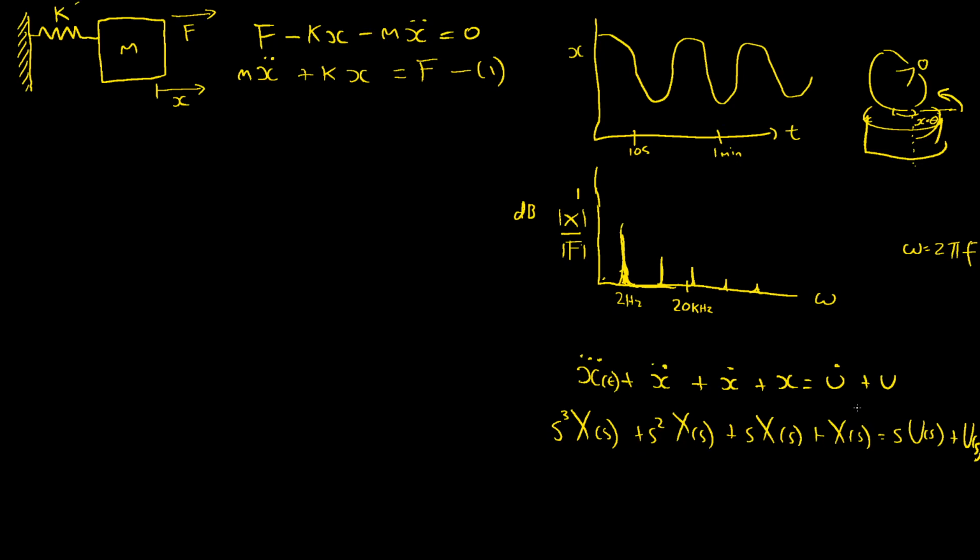So if you look up this transform when you're researching the Laplace transform, and I encourage you to, you might see initial conditions. The reason we've ignored them here and that we can going forward is because we care about what's called the transfer function of this system. So this ratio of the output to the input, this X over U, we call that G of s.